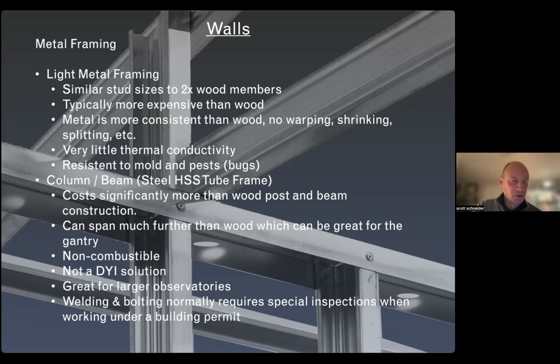The other really good thing about using metal framing is that it's a non-combustible material. So if you're in an area that is more remote, it's a really good material to use because of the possibility of fire. And then if you have to get a permit, welding and bolting requires special inspections. Any questions?